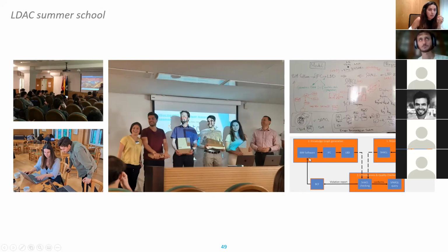Then we started with one BIM authoring tool. We converted this information to a knowledge graph. The BIM authoring tool was Archicad. Then we exported the IFC file. Then we parsed the IFC file in some linked building data ontologies. And we used also some restrictions using semantic web languages. Then we checked if the information that we need is there. Is the graph satisfying the requirements that we had? And we brought this back through a BCF viewer directly as a message to the BIM authoring tool.